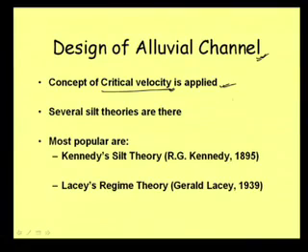They found that in the agricultural field, when canals were constructed with some expectation that they would be able to carry this much discharge, later on it was found that deposition is taking place in the channel. Let me explain it a little bit. When a canal was designed, suppose it was expected that this much flow area will be there, and sediment deposition has taken place. So its capacity has reduced. Now its sectional area remaining is only this much because of sediment deposition. So when the capacity reduces, we expected that this much water will be carried, but it will not be carried. This is one point.